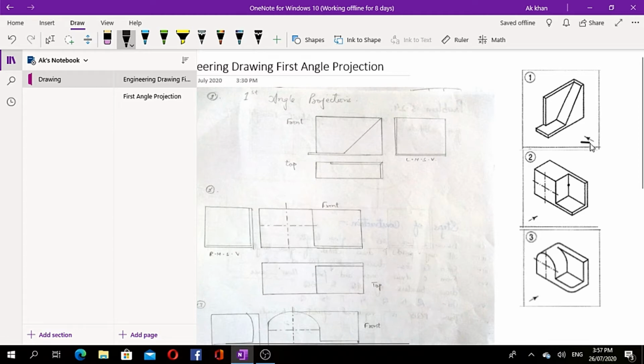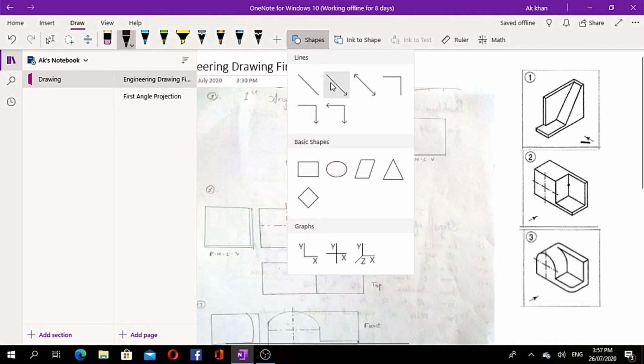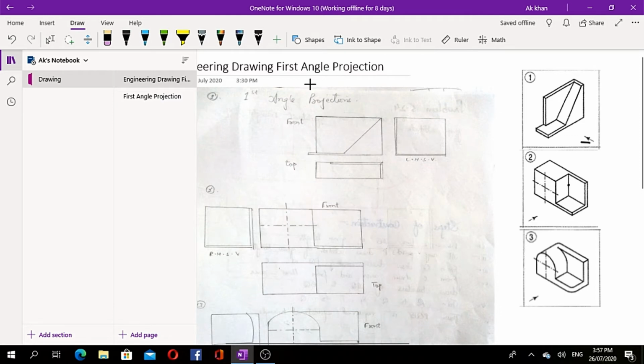Here in this case, this arrow is giving us direction. Direction of what? Direction of plane projection. That is, it is the direction from which the observer is seeing the object. So in the front view, there would be these lines only. This line and this line. You know that this horizontal line is double, so you would be drawing it double in the front view. And you know that seeing from the front side, this line would be just like that, full, and that's the line that is preceding the back line.